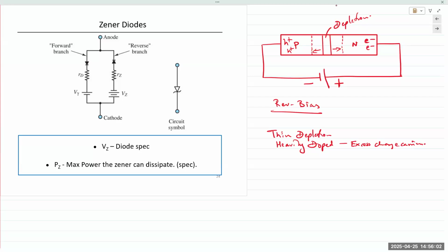In the reverse bias, this junction will not conduct like any diode junction. So the depletion region keeps on expanding. But after a certain point, the junction breaks down, and that is known as the Zener breakdown or the avalanche breakdown. This breakdown could occur due to either one of these effects. Typically, Zener breakdown occurs in very heavily doped diodes and occurs for less than 5.6 volts. An avalanche occurs above 5.6 volts. But in general, all of these are referred to as Zener diodes.